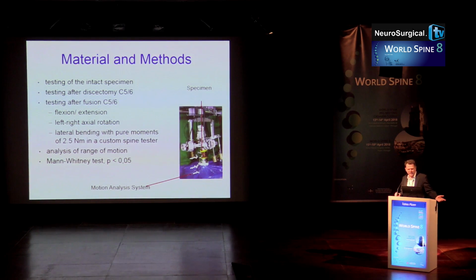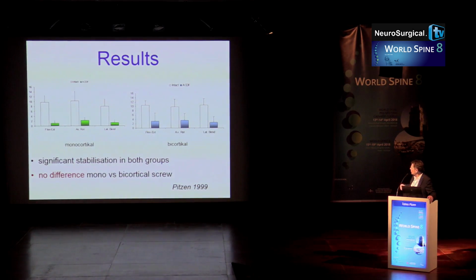And you apply not a force, because a force is acting along an axis. No, you apply a pure bending moment. The difference is a bending moment is introduced via a lever arm. You can see them here on this machine. And it's introduced perpendicular to the motion axis. So that's a big difference. So you do that, and then you store all these ranges.